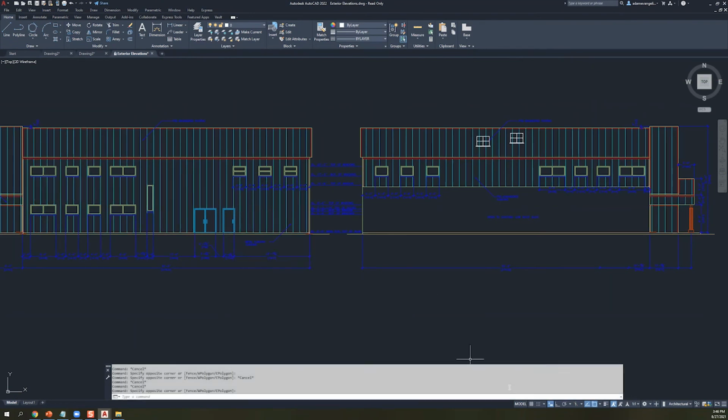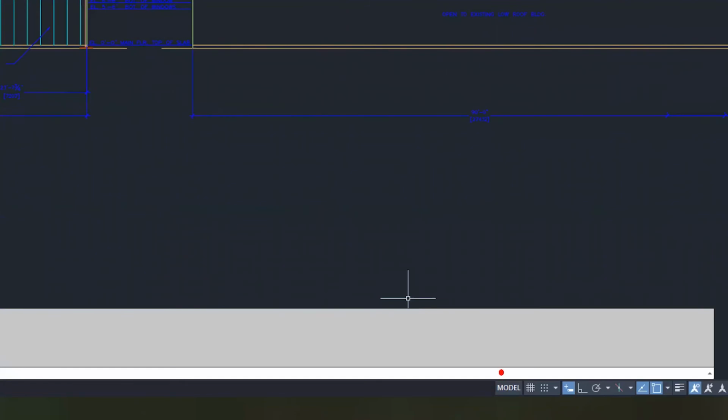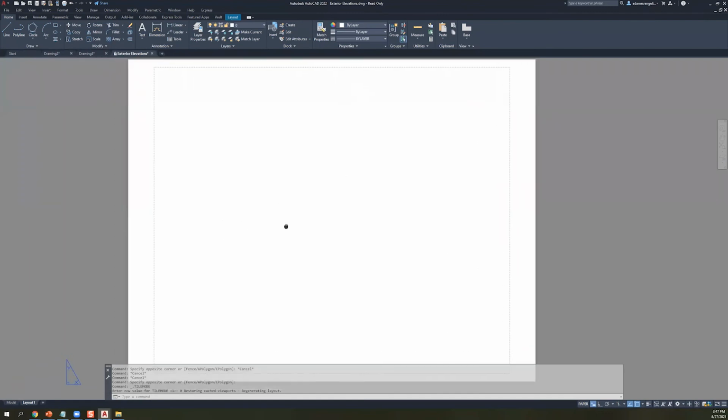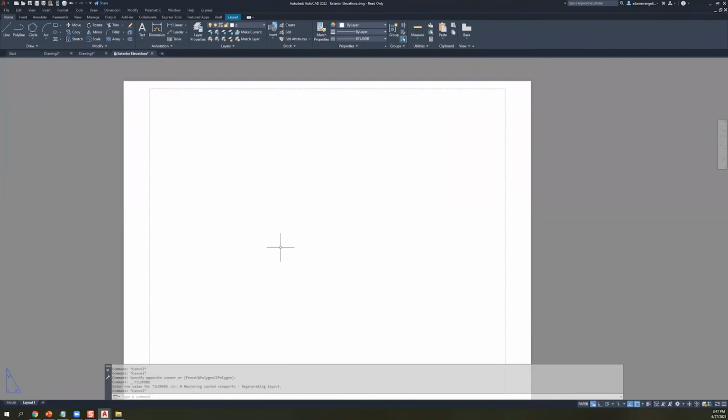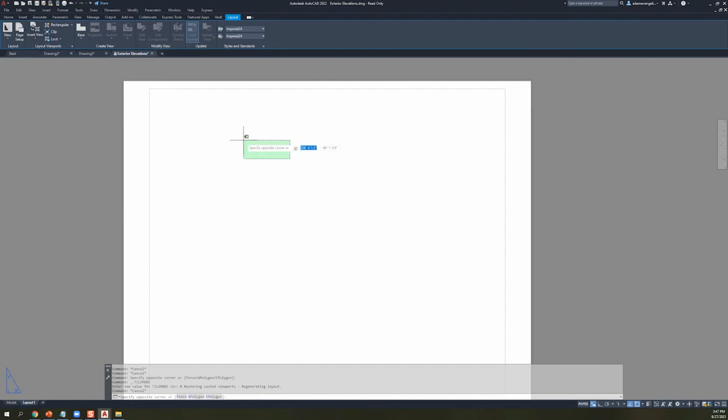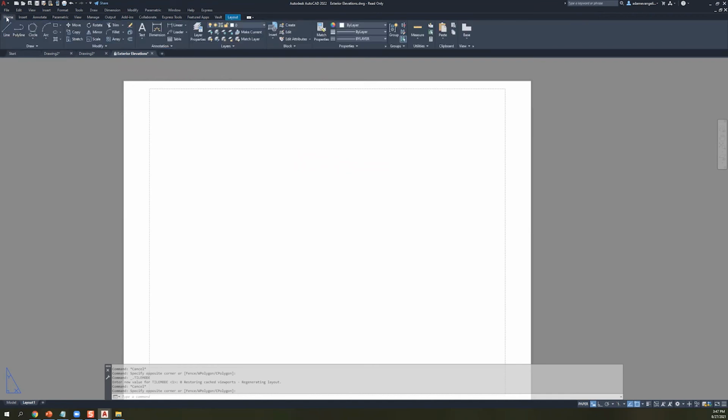We've been talking about model space. You could see we are in fact in model space down over here. Great, cool. If you want to switch, you can just click on model space and boom, we're in paper space now. Should look pretty different, right? And you'll notice you have all your regular tools up over here, if you want to do regular sketches. We also have a layout tab now, which will allow us to do certain things in the layout view, right? A lot of extra tools over here that I'm probably not going to talk much about. There's only a few that I really need, but layout space is a different environment. Paper space is a different environment where we're going to have to abide by a few different rules, keeping in mind the real world implications of what we're about to do over here.